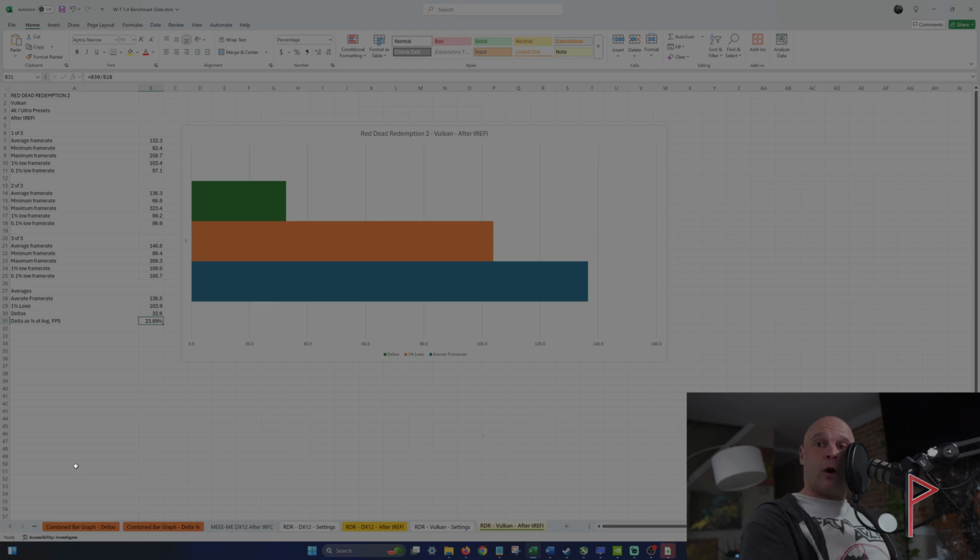And I didn't even blow them up. 80,000 it's sitting at. Okay? I can push it much further. Same with tRFC. tRFC2 at 470, tRFC at 370. That's nothing. And you saw what it did. Those are just the refresh timings.